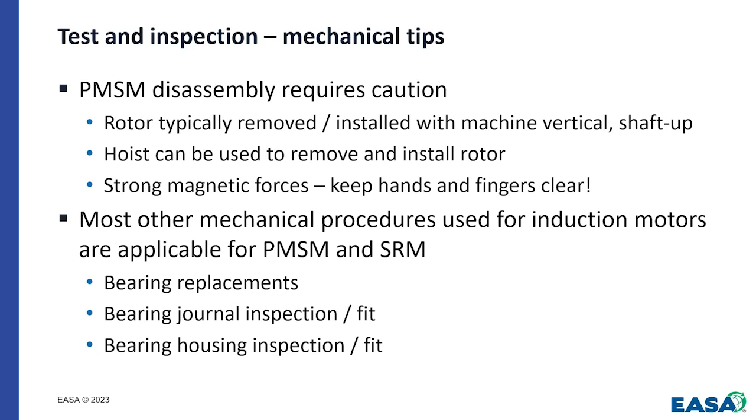Never put your hands or fingers or anything like that, certainly in the way of the rotor and any magnetic steel materials or the stator. Outside of that, most of our standard cleanup and refurbish type jobs, we can do these the same as we would do any induction motor. So replacing bearings, checking journals and housing fits and all that good stuff, we can do that kind of work the same way.